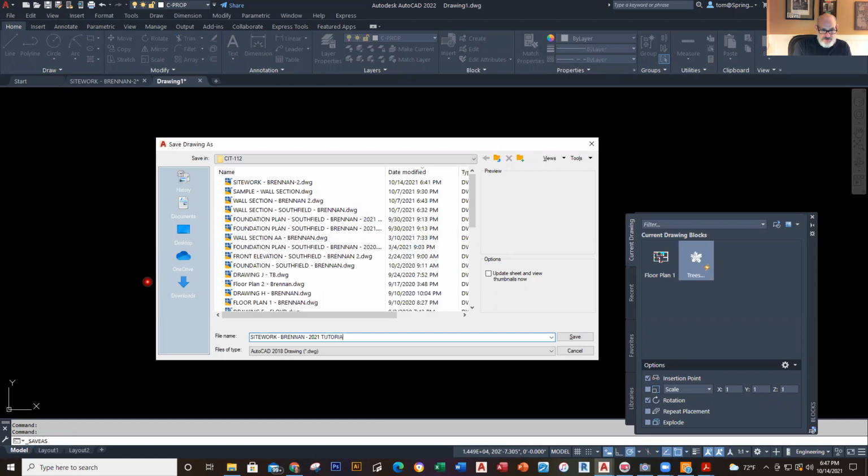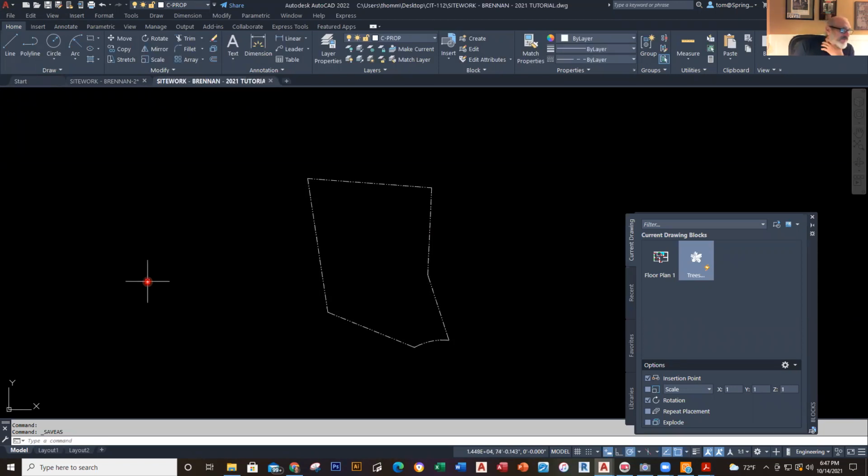Professor? Yeah. So I was following along with you. I don't know if this happened to anyone else, but when I put in the left side 96-foot measurement, I've tried it 3 times now and it keeps going north instead of south. Yeah. Okay. Now, when you're doing that, just make sure you're doing this. When you're starting and you're at this point right here, you're coming from here right now, you want to make sure you do it in this way, which is you're going to type in 96.09 feet and then less than.